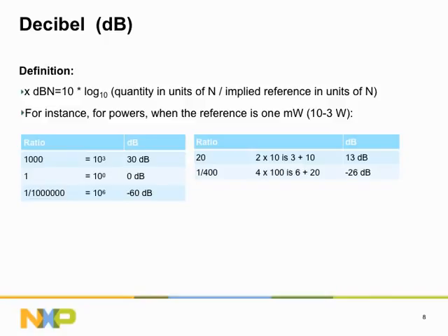Likewise, if an amplifier has a gain of 20 dB, it amplifies the signal power by a factor of 100, right? This allows engineers to go through the gains and losses in a system in a very fast way, by adding numbers that are easy to handle. I know this sounds clumsy at first, but after a few years, it's easy to do math in the dB domain, and you become thankful for it. You'll see how this is used in further presentations.